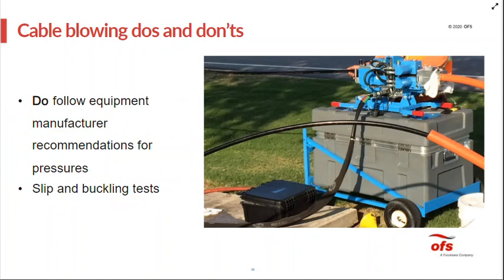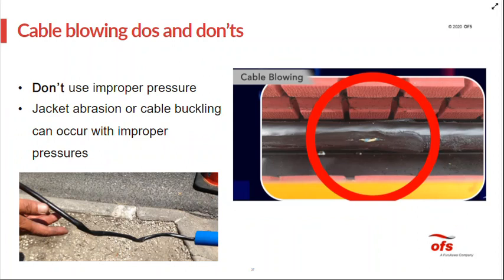Do follow the manufacturer recommendations for pressures. That's both for air pressure in the duct as well as the drive pressures, whether it be air pressure or hydraulic pressure on the drive track or the drive wheels. But also in addition to that, it's always good to conduct slip tests and buckling tests using the cable just to ensure that you don't over push the cable, possibly slipping the tracks on the cable or buckling the cable. We're going to see some photos of that in the next slide.